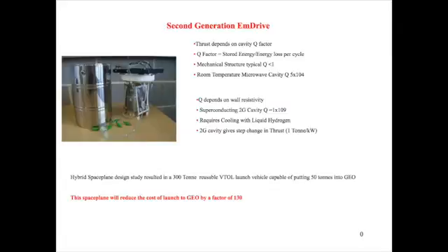There's a big advantage in this because using liquid hydrogen to cool the cavity means that as you boil off the liquid hydrogen, you can make use of the hydrogen gas in a fuel cell along with a bit of oxygen to produce your electrical power. And in the early designs of space planes, you can see that the hydrogen is also used for auxiliary propulsion.